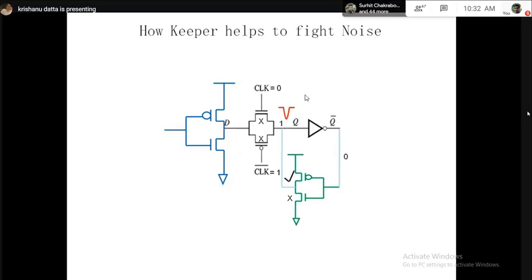So this means if there is any circuit noise, let's say a down glitch, right? It is holding 1, and some glitch comes. In a circuit, the noise is always in the form of a glitch. Now, when the glitch appears through various reasons, what will happen? This PMOS is on, and Q is connected to VDD by the PMOS, so the PMOS will fight this glitch and ensure that the output Q is always a strong 1.